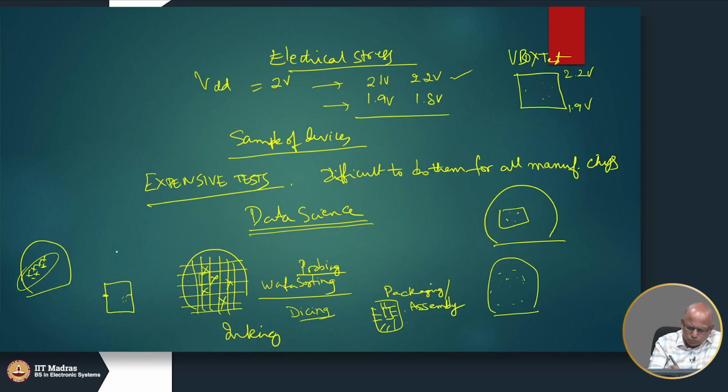They call these shmoo plots. Shmoo plots means a plot which shows which chips are bad. The connectivity of these X marks may lead you to conclude something about what may be going wrong in the manufacturing.